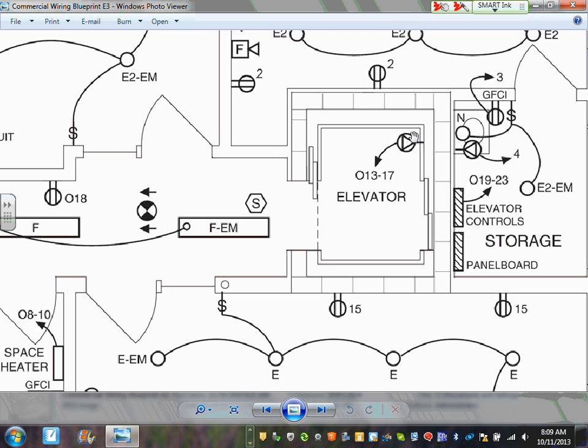And all these will be decided by the architects. At the beginning, the architects will decide with our engineers when you sit around whether this building requires an emergency generator. Yep, so we'll provide the emergency generator for them. So typically the emergency lights, guys, exit signs, egress lights, and elevators for most of the building. If you go to the hospital, it's a whole different area. They have receptacles also in the emergency system. They have heating and cooling in the emergency system because people are sitting there. They can't leave.